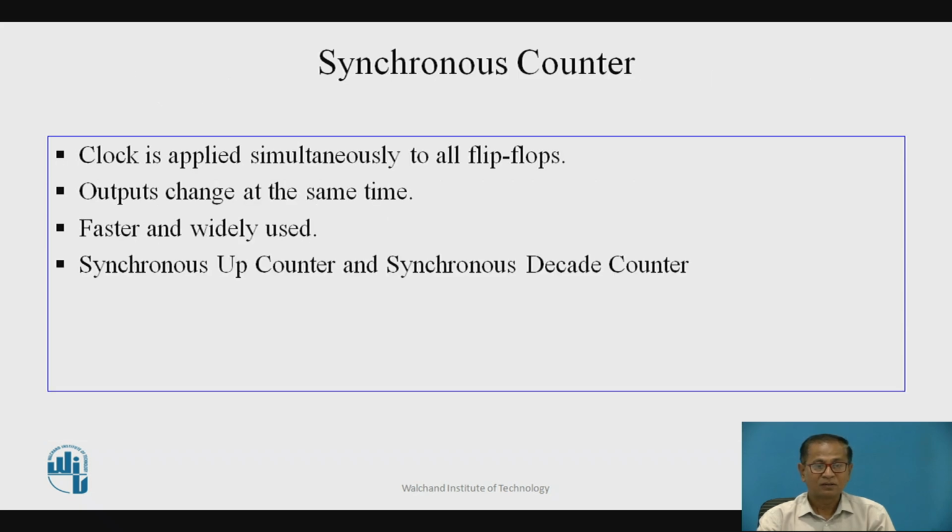Synchronous counter. In this type, the clock is applied simultaneously to all the flip-flops. In the synchronous counter, the output changes at either the rising edge or the falling edge, and the outputs change at the same time. So synchronous counters are faster and widely used in industrial applications.